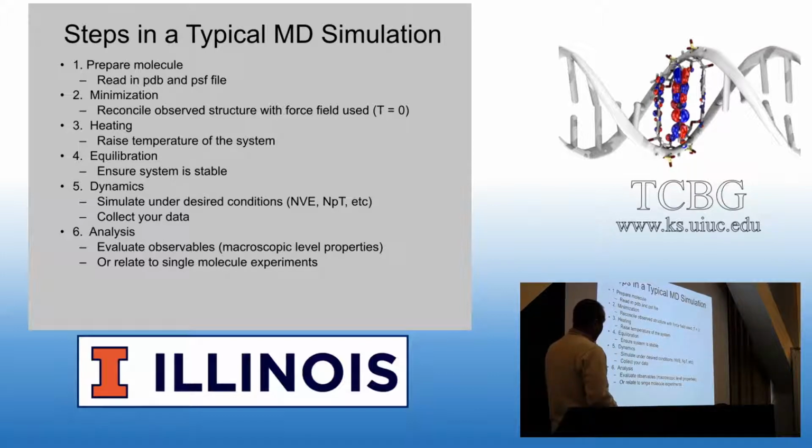So in the beginning of the simulation, usually the first picosecond or so, things can get tricky. But be patient, just do some tricks. Maybe you can even take smaller time steps to pass this critical phase, and then after that, usually things are easy. Equilibration. So then you have to equilibrate the system to reach a state in principle.